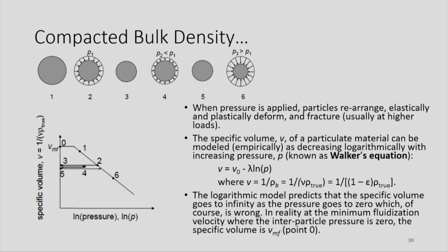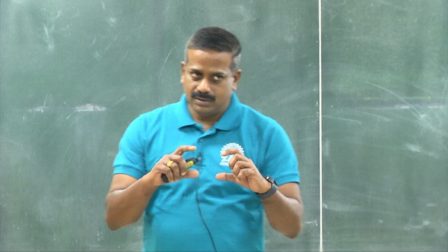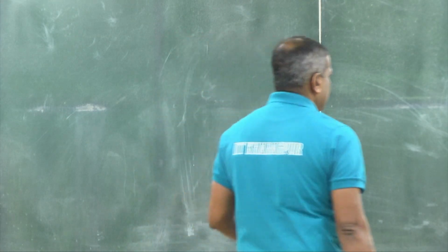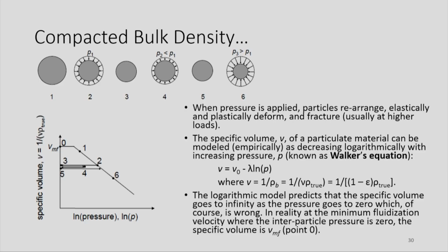Again, it depicts the change in plasticity and elasticity of the powder, or plastic deformation and elastic deformation of the powder, and how it relates to change in volume when you are compressing the powders. Okay. So again, there will be a sudden change in volume when there is a high level of plastic deformation. Okay. Then again, the volume will not change until it reaches the final maximum density.